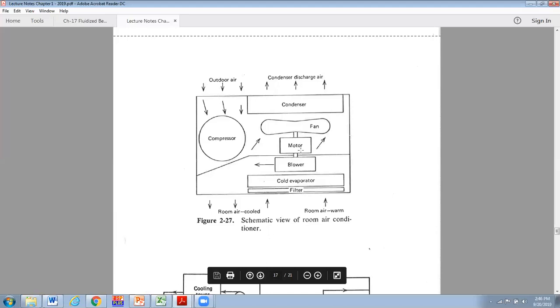And then on the other side, so again, we have a double shafted motor. So it's turning both this fan and a blower that will suck the return air on this side. There's a baffle that partitions off the two sides of the unit. This is our evaporator, our cold coil. Got a filter in front, and it simply pulls room air, cools it down, and blows it back into the space. Got some pretty unsophisticated controls, and that's pretty much what the window air conditioner does.